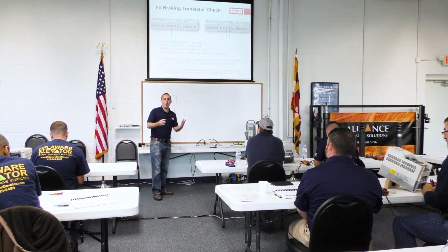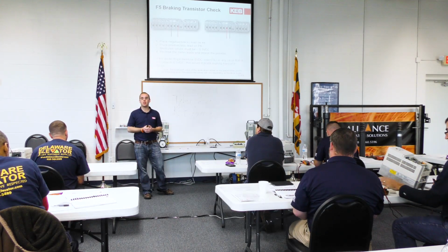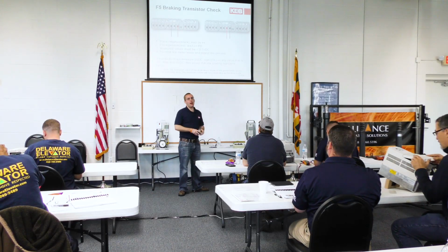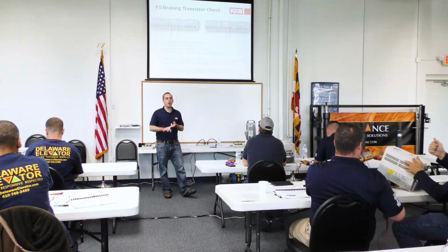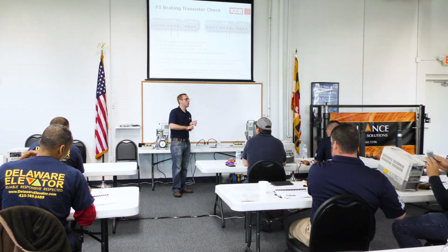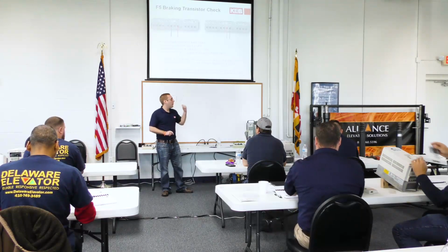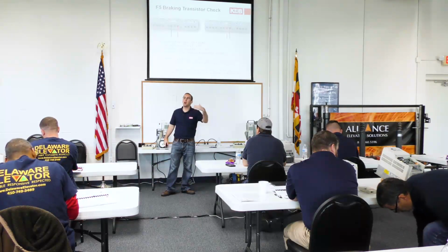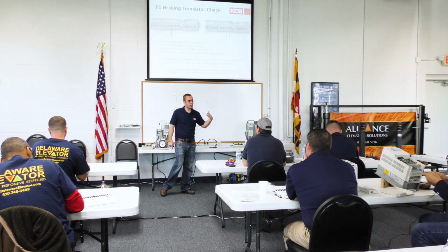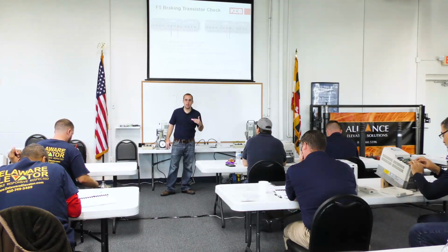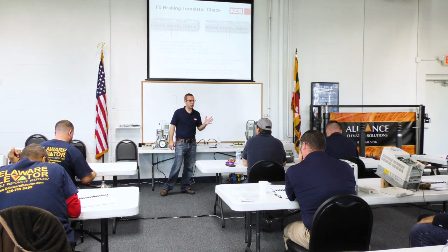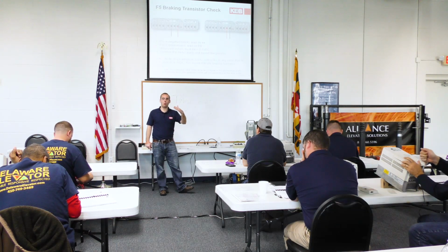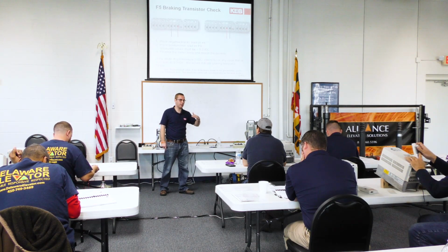Okay, if you guys want to put your meters away, that's going to conclude the diode check part here. This procedure is outlined in our manual as well, along with the recommended voltage drops that you should see. The 0.3 volts is what you should see for all these drives here. However, some of the larger drives have a different value, and you might be seeing an open, especially across the braking transistor for some of the larger drives. We have indicated in the manual what values to expect for what size drive you have.